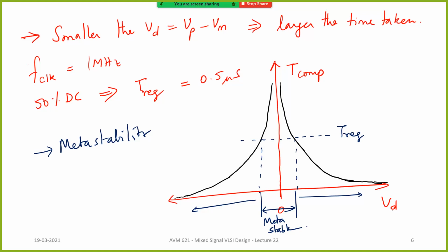For example, for a 1.2 volt system, anything greater than 0.75 can be very safely interpreted by your circuit as logic high. Anything lower than, let's say, 0.3 volts can be safely interpreted as a logic low. So instead of giving 1.2 volt, you can always give VIH or VIL, which is the tolerance of your logic voltage levels.